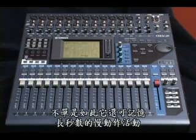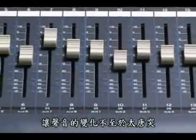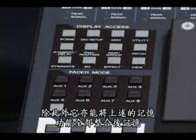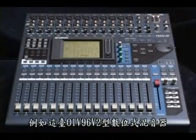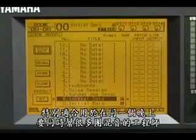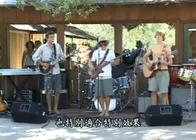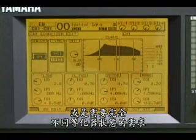Although, as you're probably starting to understand, mixing is more to do with setups and slow movements than rapid changes to your sound. There's no denying, though, the power of being able to recall these settings at the touch of a button. Here on the Yamaha 01V96, for instance, you can recall multiple scenes, complete with effect settings, and this is a wonderful facility to have, especially if you're mixing several bands in one night. But it's also extremely useful for particular effects. A different range of EQs on a ballad maybe.